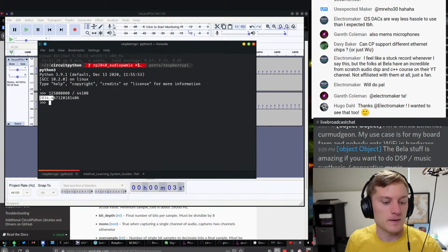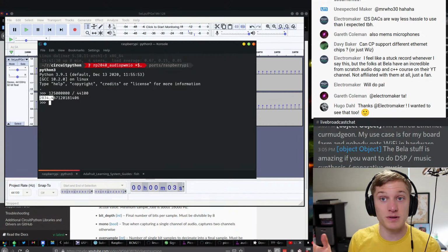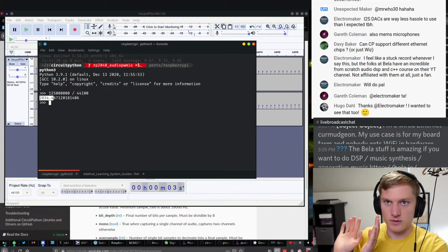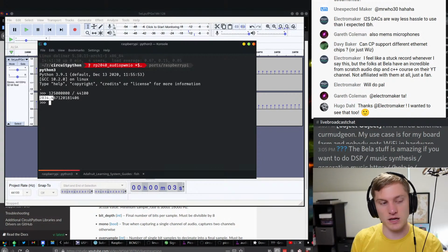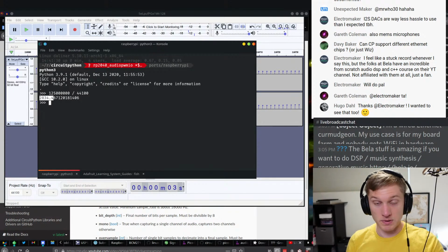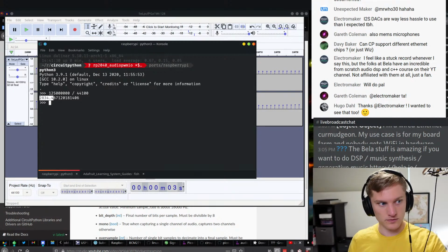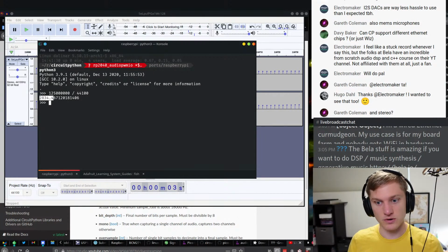So generally CPUs have a problem being consistent, right? This is why the PIO is so interesting, is that it's something separate. It's not getting interrupted. It's just running at a fixed frequency. So if this was our PIO, which we can also run at 125 megahertz, we have 2,800 or so things that we can do.